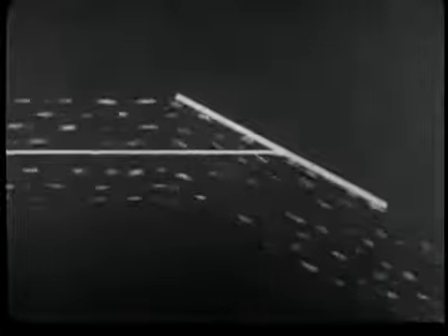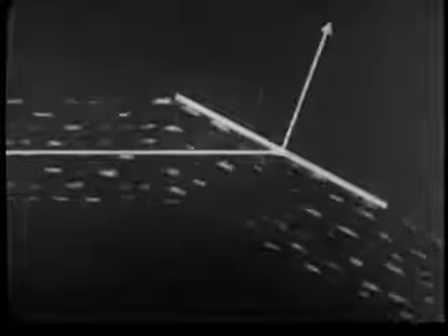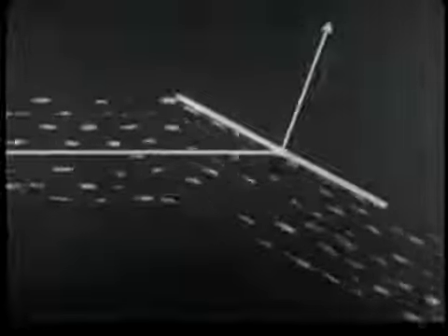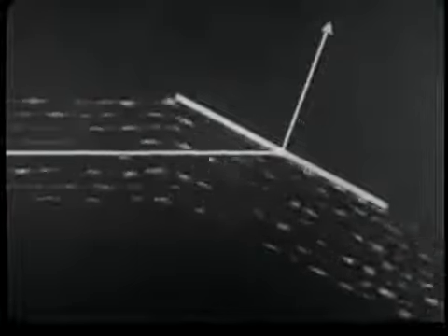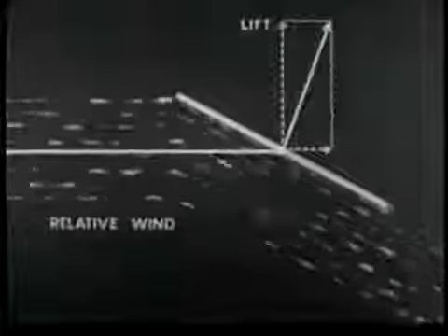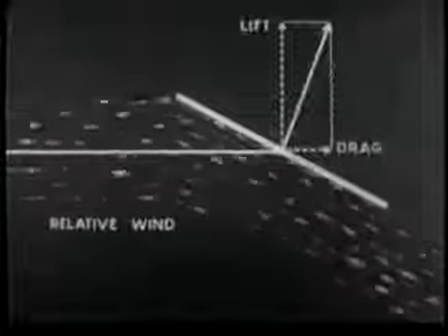An airfoil is any surface designed to be projected through the air in order to produce a useful dynamic reaction. A stream flowing past a flat plate exerts upon it a force whose direction depends upon the angle between the plane of the plate and the direction of airflow. This force may be analyzed into component forces, which are called lift and drag. Lift acts at right angles to the relative wind, and drag acts parallel to the relative wind.